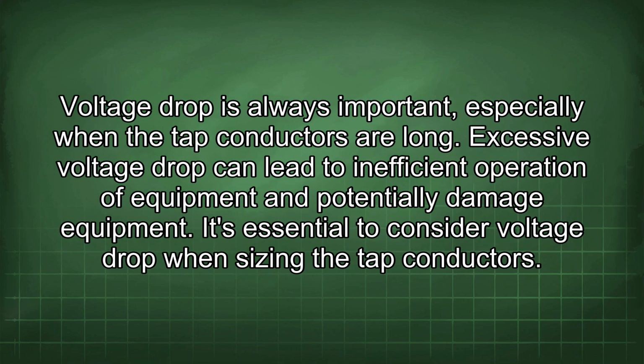Voltage drop is always important, especially when the tap conductors are long. Excessive voltage drop can lead to inefficient operation of equipment and potentially damage equipment. It's essential to consider voltage drop when sizing the tap conductors.